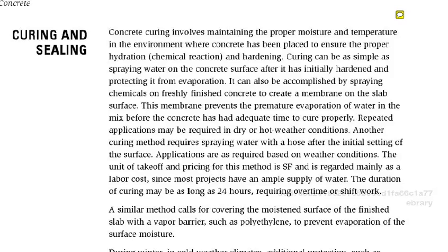Sealing will go on sometimes again with a curing compound, but sealing also can go on later. What it's intended to do is to hold the surface of that concrete in place, especially where you don't want dust to get away from the concrete, or oils or other materials that you may be working on, say a floor of a garage.